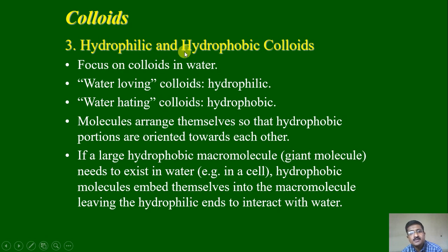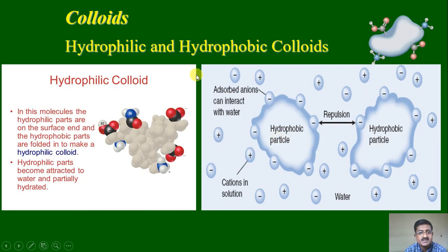So this hydrophilic and hydrophobic nature of the colloids is responsible for the coagulation process, or the settling action of the particles, and that depends upon the interparticle attraction. In this figure you can see the colloids described as hydrophilic and hydrophobic colloids.